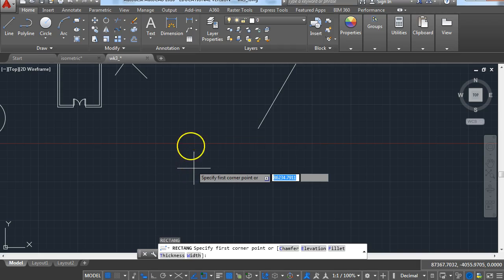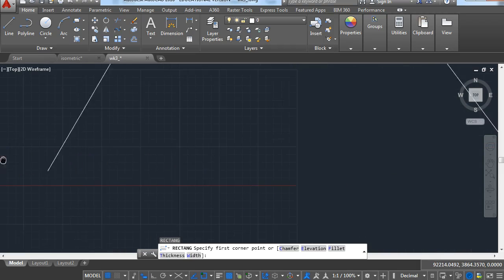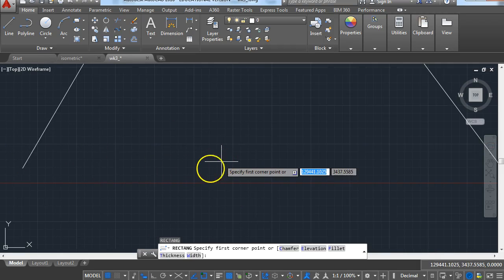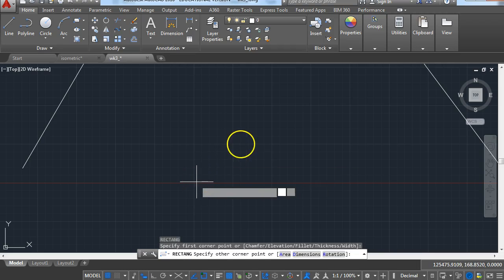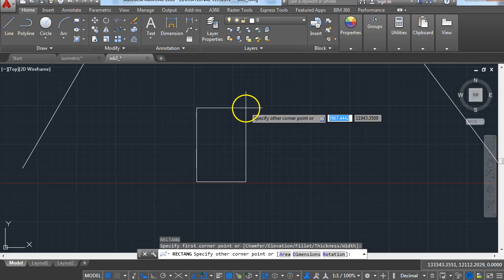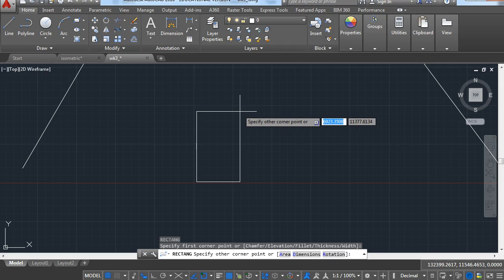and it always asks you for a start point. Generally I use the bottom left hand corner for this. So start there, and then you can either place the next point by a click of the mouse, or you can enter the dimensions using the keyboard, and therefore you can quickly enter the dimensions of a room if you would.